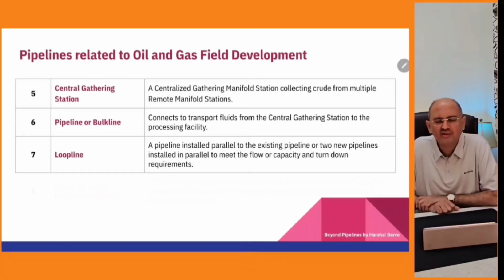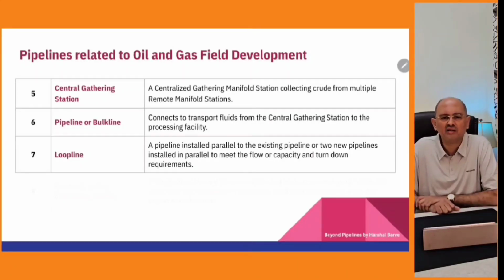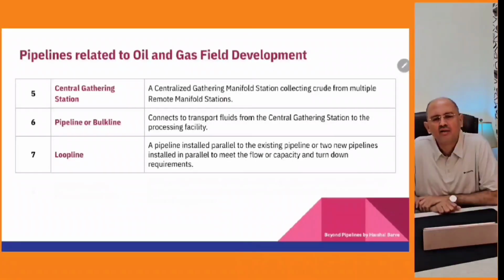So basically, in order to make sure that throughout the design life sufficient flow rate or velocity of the fluid is achieved in the pipeline, so that its corrosion is kept under control and its corrosion prediction, pigging and maintenance become relatively practical, many times a loop line concept is designed by the hydraulics people. That is normally done by the process team in discussion with the corrosion team and the pipeline team.